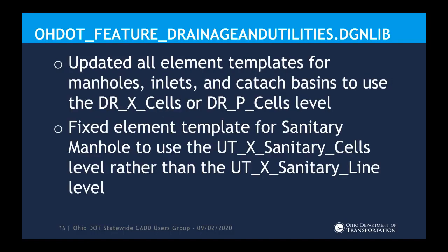All right, and lastly for the drainage, all manhole, inlet, and catch basin element templates were added or updated to use either the drainage existing cells or the drainage proposed cell levels. And the sanitary manhole element templates were fixed to use the sanitary cells level rather than the sanitary line level. There were a few other updates that I omitted for drainage, so be sure to check the running update log. And feel free to reach out if you have questions on any of those.